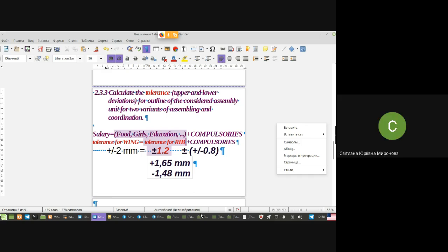Very well. Then answer the question, please. We are comparing what we have got with demands. Demands, red color. Tolerance that we have calculated, we recalculated aggregate tolerance for our own tolerance, for the panel or for the rib, whatsoever we're working with. We see that the demands of the designer to assemble this rib, panel, rib, spar, is not worse than plus minus 1.2 millimeters.